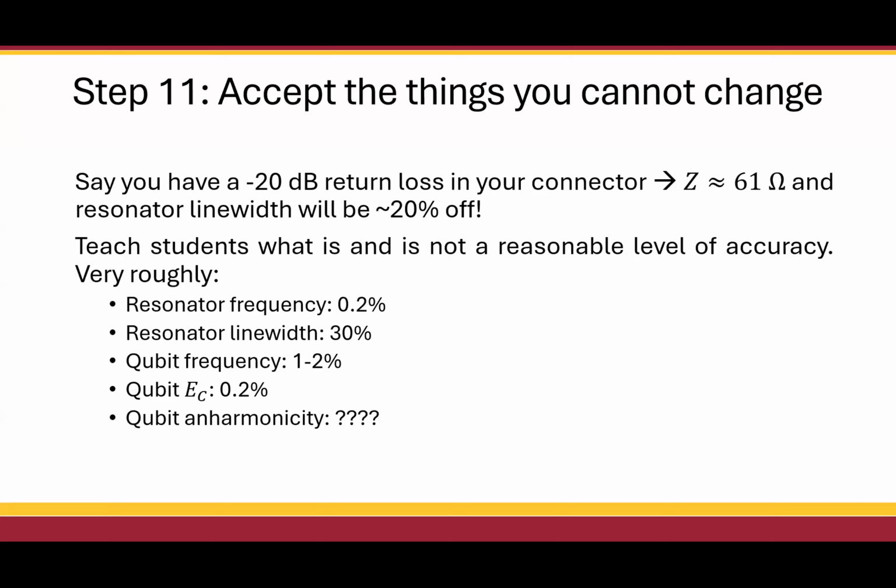I think there were some questions online. Oh, sorry, I missed these. These were kind of a ways back. One was how much of fabrication should you cover? I would say only enough to say what's reasonable to hit in terms of repeatability. You can go into fab as a special topic, but I think designers only need to know it in the sense of what is and is not possible. And maybe at the end, just talk briefly about how to account for fab bias, how to account for the fact that when you draw a GDS file, the actual features that get created might be a little bigger or a little smaller.